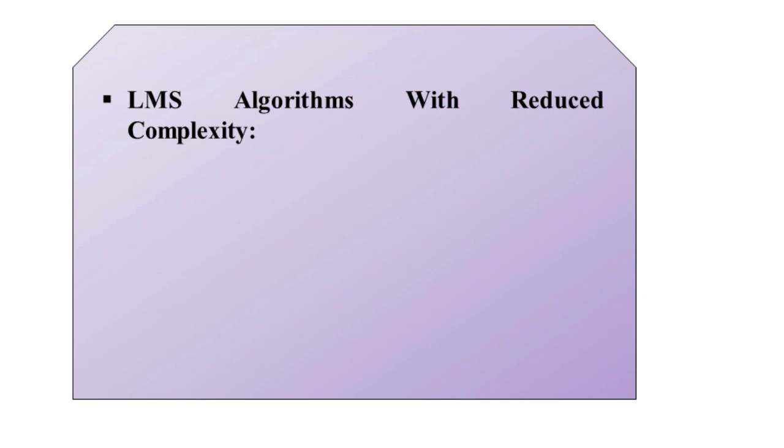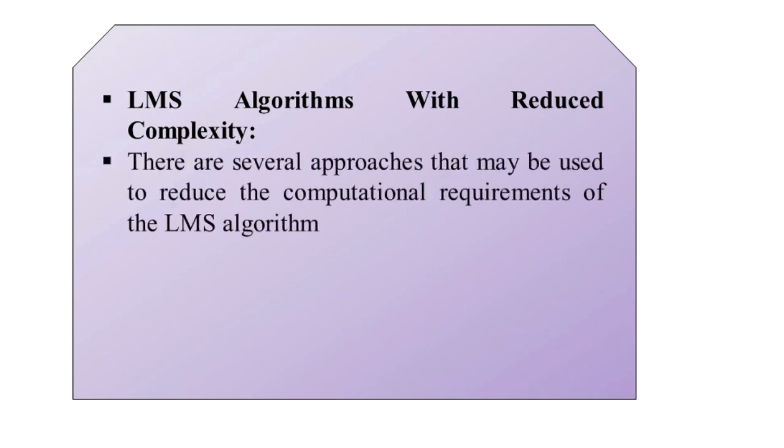There are several approaches that may be utilized to reduce the computational requirements of the LMS algorithm. If we talk about the block LMS algorithm, it is identical to the LMS algorithm, except that the filter coefficients are updated only once for each block of capital L samples.